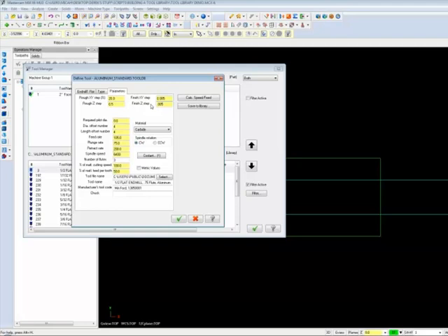We'll dial back on the feeds as well. We'll set 75 inches a minute for feed rate and 50 inches a minute for plunge rate. Since this tool is based off our other tool, the material and the coolant are already set up the way we'd like. Rename the tool to reflect the 2-inch flute length. And enter the correct tool code, 138-50005. Instead of clicking OK, click the Save to the Library button.